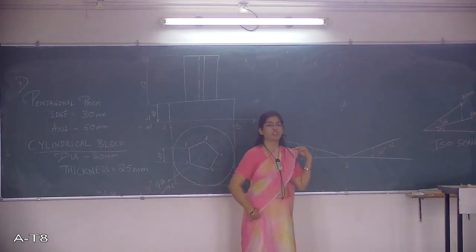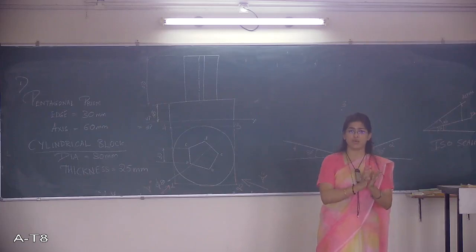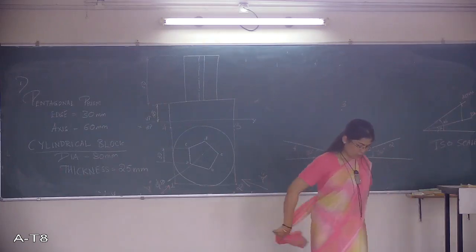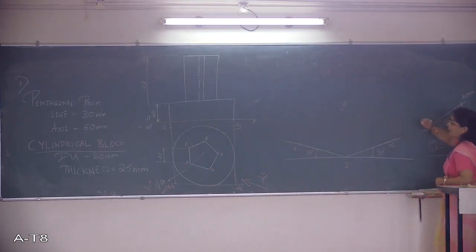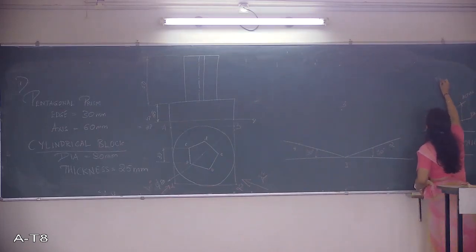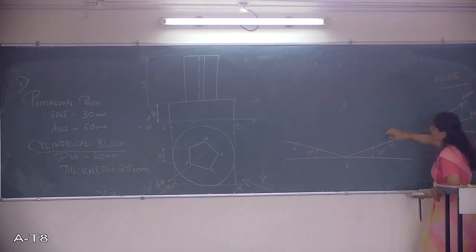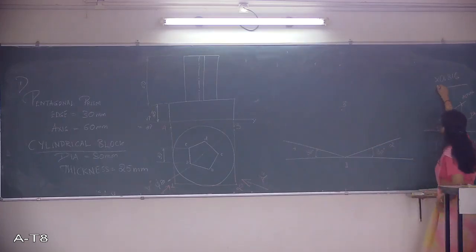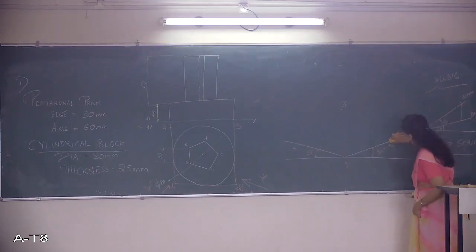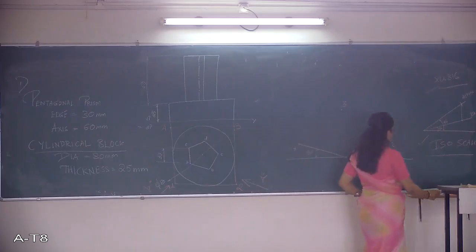In isometric projection, every dimension on the actual scale has to be converted to iso value, that has to be marked. So here basically, instead of going to the iso scale, if you are not comfortable with this, all the actual dimensions you can just multiply by 0.816. The value that you get is this value, the new measurements that I have marked. You either go for this one or you go for this iso scale and mark the iso scale dimensions on this particular.